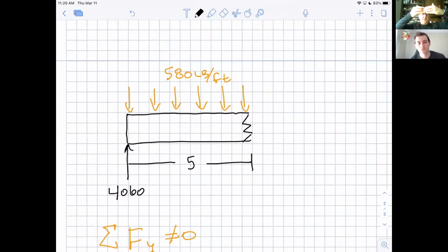So here's my beam. Let's pretend it's connected in the middle. Why can't this side of the beam move down? Well, because it's connected to this side of the beam. Like, this can't move down without this one moving down too, right? So if this side wants to move down, isn't this side lifting it up? Like, it's connected to something. So there's actually a vertical force there by connection, right? This side can't just slide down with this side not moving because of the internal structure of the beam.